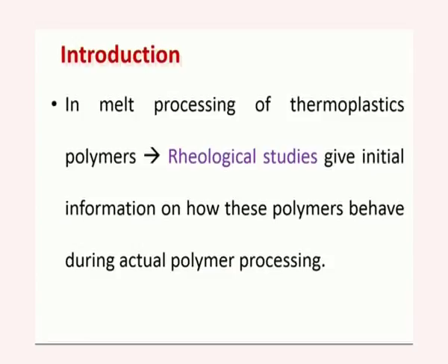And also the rheological studies will give information on how these polymers will behave during actual polymer processing. Before we go for processing itself, later on we will see that the rheological properties are simply understood with respect to a plot between shear stress versus shear rate. So, the shear rate is important. What is the rate at which these viscous liquids are sheared, either in an extrusion molding machine or in a blow molding machine? That is where the rheological studies help.